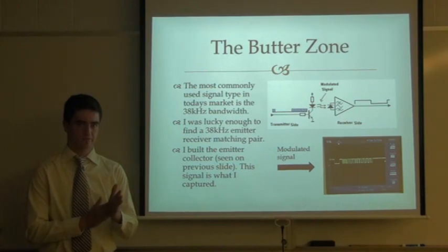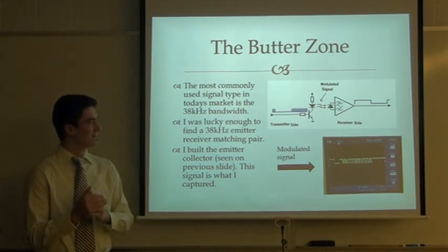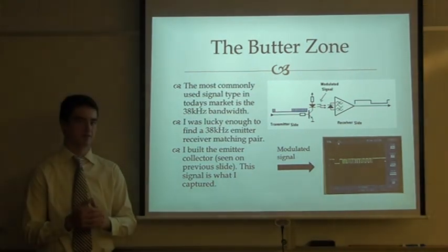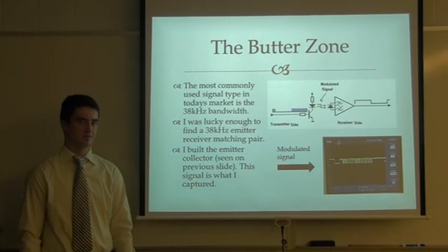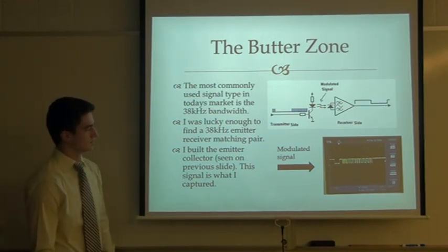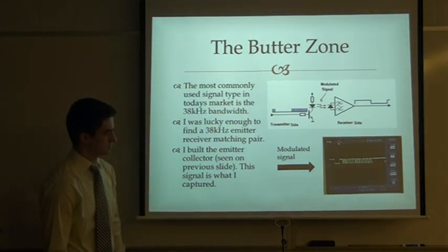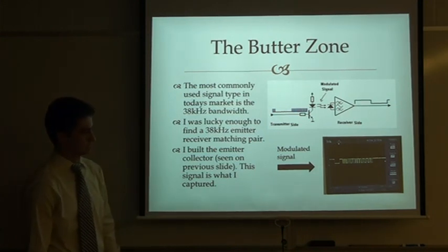I just wanted you to explain that better, because you have two diagrams that are not at all consistent with each other. So if you're going to label that upper one, each of those little blue pulses would be like 25, 27 microseconds apart. And you can do the math: 27 into 10, because it's 10 milliseconds for that first pulse in the lower diagram. So there are 50 or so of the 38 kilohertz pulses in there. Right. Yeah. All right.